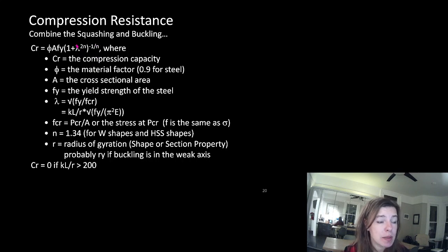Lambda is basically our buckling factor. That's what I usually tend to refer to it as, our buckling factor. So look at this. Here's that equation we had looked at on the other page, slightly rearranged. It's really just about the yield capacity relative to a critical stress that it would buckle at. Don't worry about it too much. Here's the equation we're often going to use.